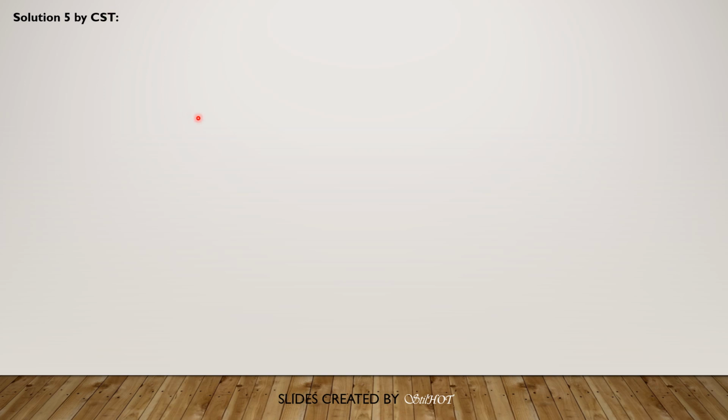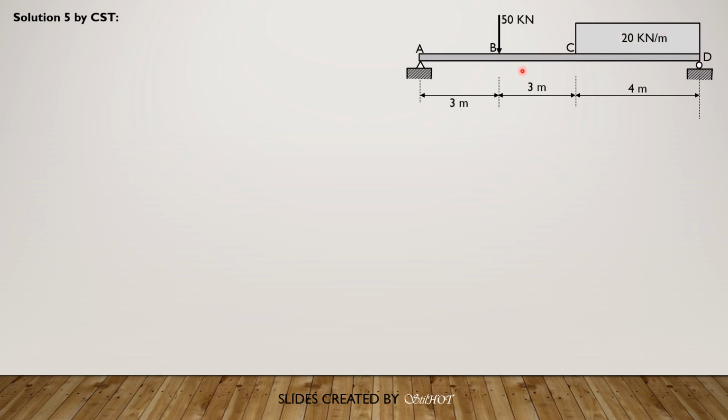So this is almost the same as the virtual work method. Instead of applying unit virtual load, we apply actual load but assumed loading, invented loading. So first, we have to apply a couple at D. Remember that the reaction here is equal to 51 upward. So due to the couple, reaction at A times 10 equals couple. Therefore, the new reaction at A is 51 plus 0.1 of the couple, or 1/10 of C. Then similarly here, it's 79 minus 0.1 of C.